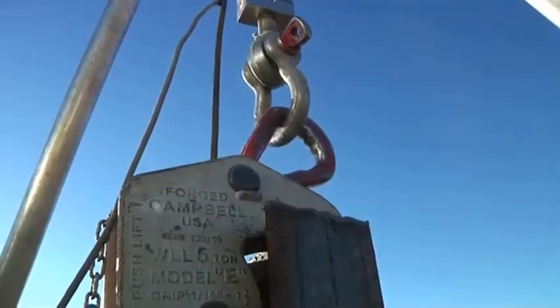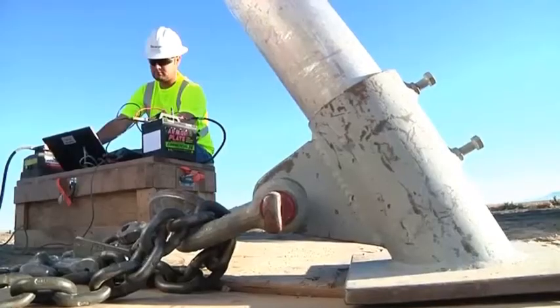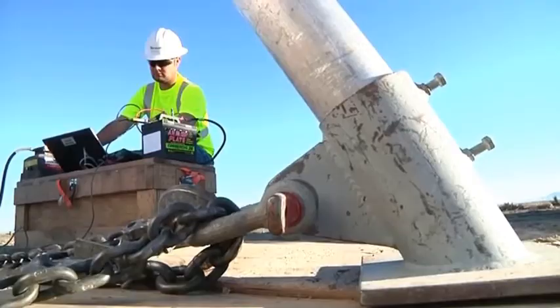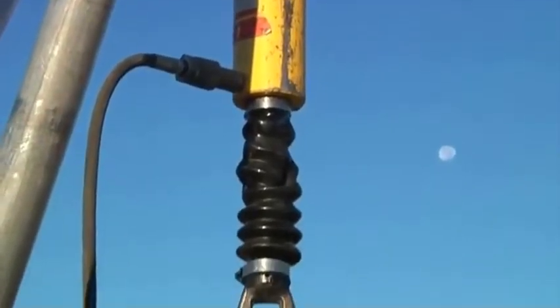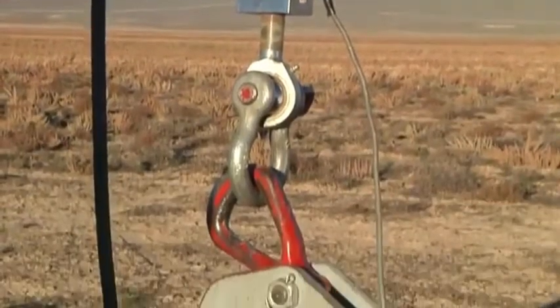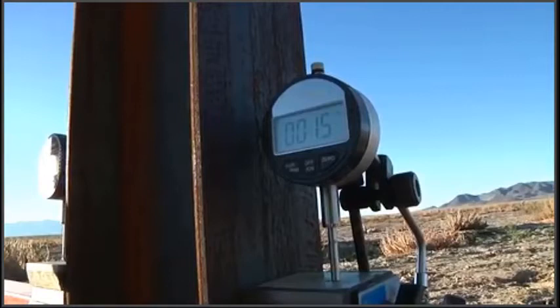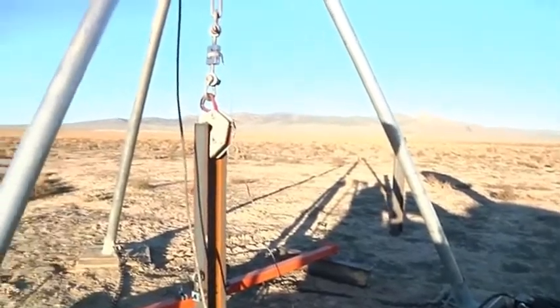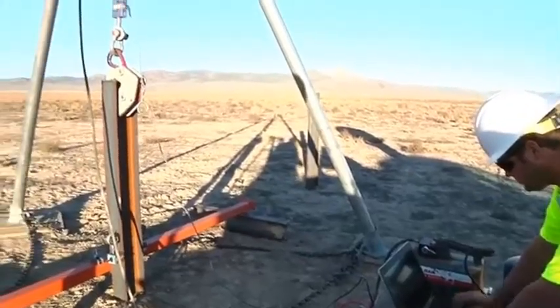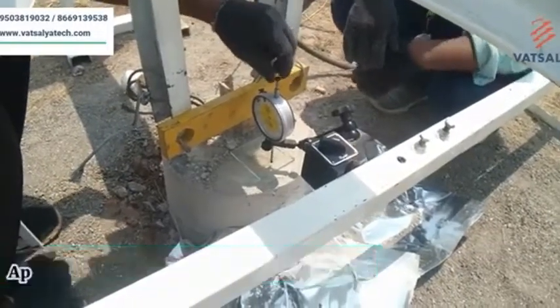For example, if the design load of a single pile is 60 kN, a load between 90 kN and 120 kN will be applied to lift up the pile, and the vertical deflection or uplift will be read using 2 or 4 dial gauges. The readings taken on the dial gauges will be manually recorded at an interval of 15 minutes or 30 minutes. This record will then be used to analyze the test to determine if the pile passes or fails. Some companies use a hand-driven hydraulic jack to load the pile.